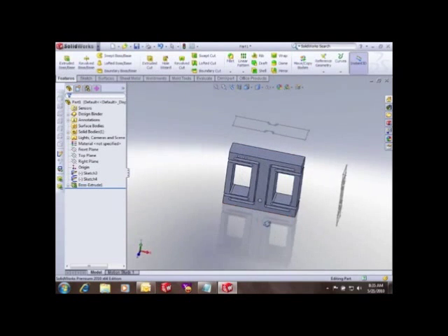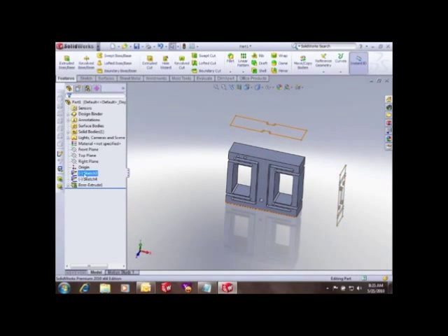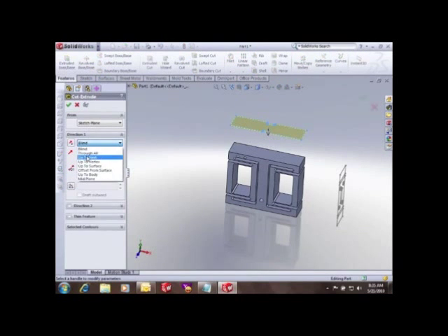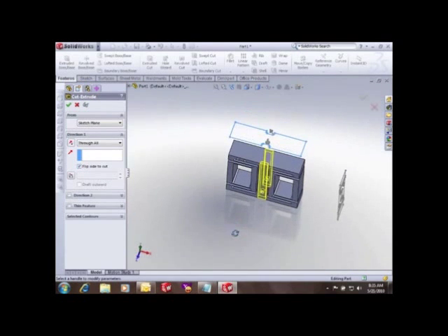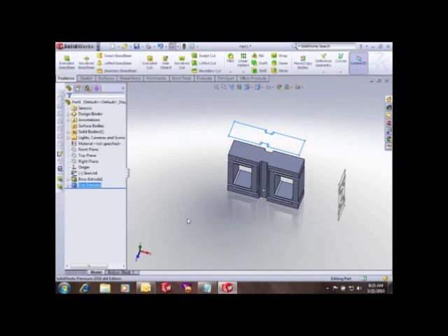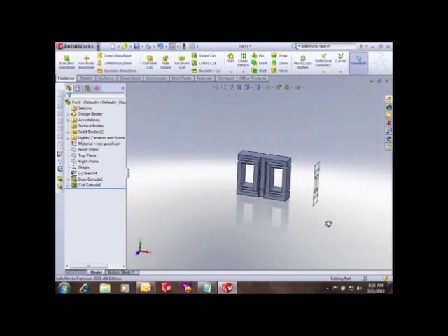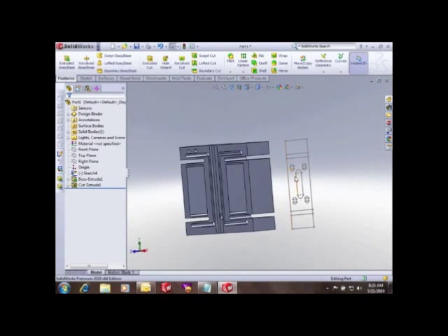Okay, now I'll go ahead and use the top sketch as a sketch to cut with. So I'm going to cut it through the entire model, and I'll flip the side to cut so it cuts the outside away, leaving these little troughs in the 3D model. And last I want to go to the right view, and I want to cut out these slot shapes in here. So what I'm going to do is select that sketch and use it for a cut extrude.